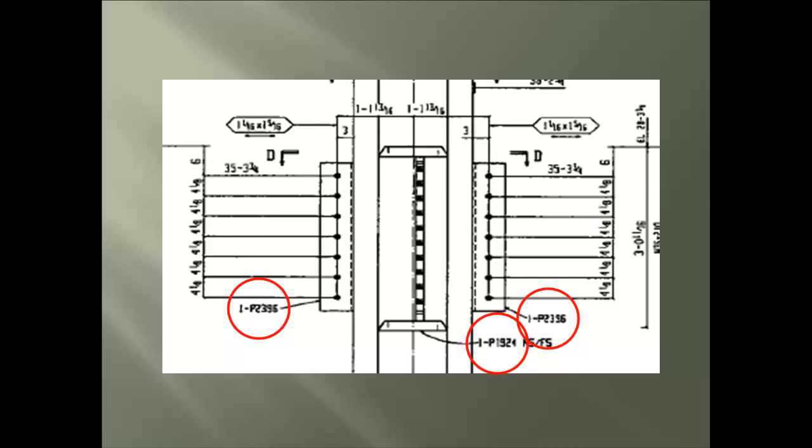And lastly is the connection plate found on the other side of the column with the number of P2356, and the identification marking should be there too. The thread that ties these three examples together is that they will be found on the bill of material box under the piece mark number column. If not, once again, some investigation is required.